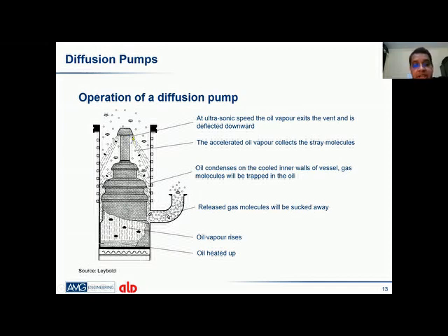These ejectors will generate a very high speed, a supersonic speed. Because of the high speed, a localized vacuum is created in these areas, and whatever particles are inside the furnace are dragged and pulled down to the bottom. And this is an exhaust of the diffusion pump, which is now connected to the roots pump and the booster pump.